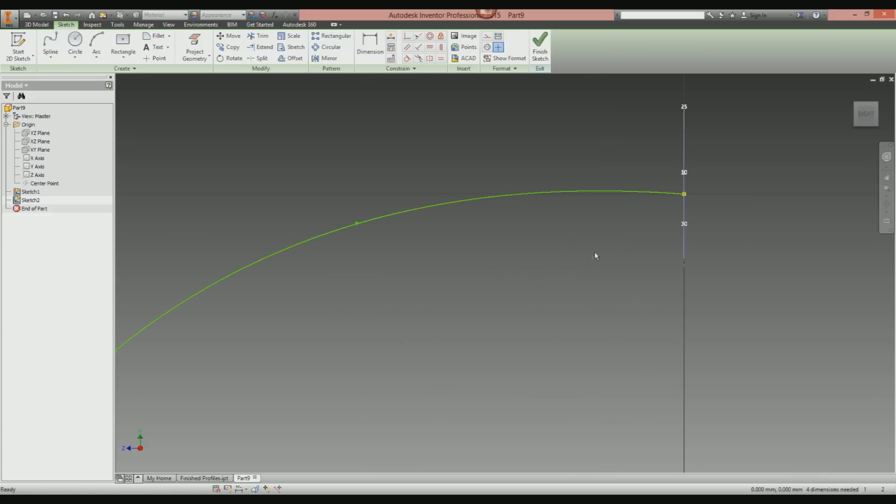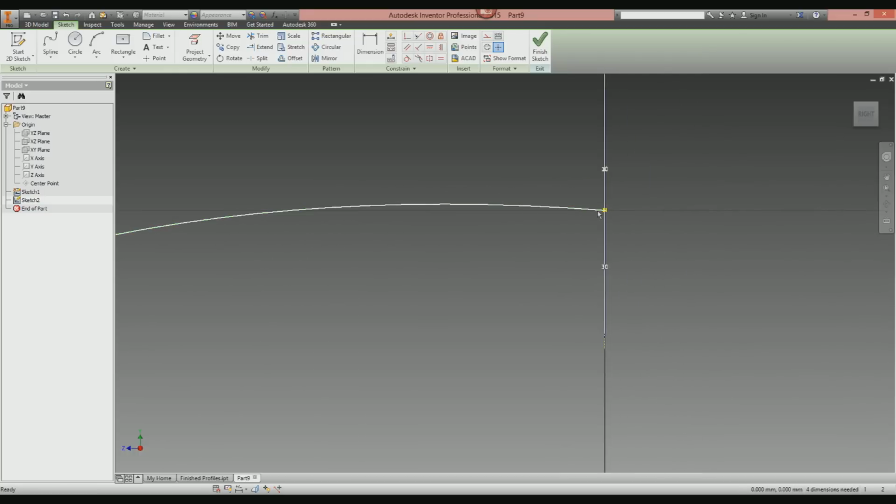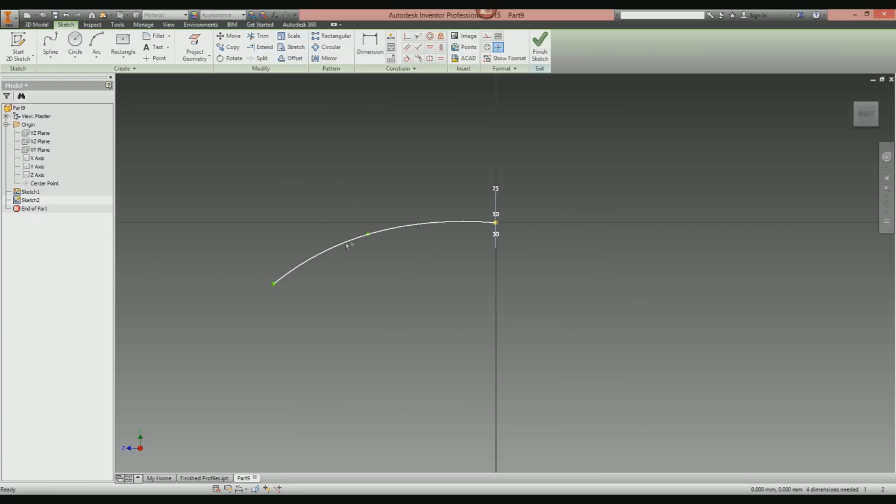However, if you look at where the spline comes out of the profile, can you see it sort of bends up before it goes down? That's not good. I want it to come out perfectly normal from the sketch plane. I want it to be a smooth transition out and then down. Because if I do loft a profile along this line, it's going to kind of go up and then it's going to go down. It's not going to terminate against this sketch profile kind of perpendicular or normal to that sketch plane. So we need to sort that out.